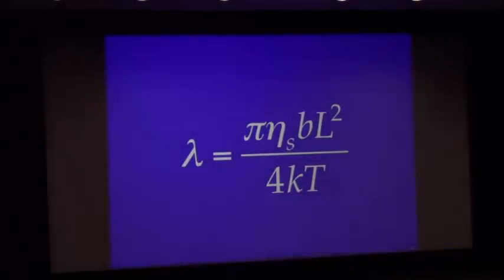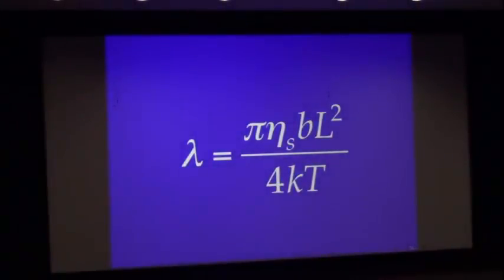When I take the continuity equation, right, every molecule has exactly one orientation. So the relevant continuity equation here is that. And when I take the continuity equation and make it dimensionless, this relaxation characteristic time jumps out. And it goes with the length of the molecule squared. Think molecular weight here. So the polymer contribution to the stresses will go with a characteristic time that goes with L squared. B is the width of the molecule. That's the diameter of the beads.